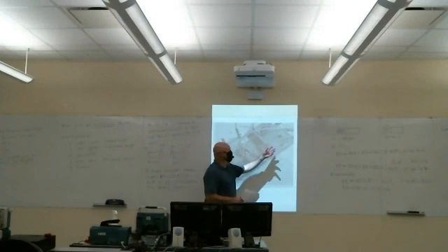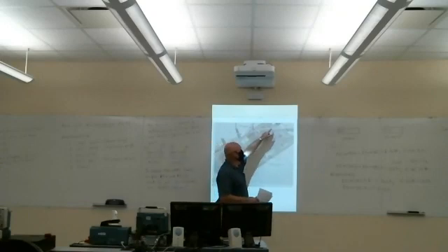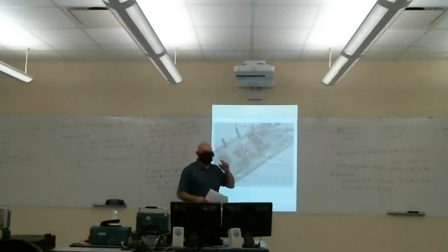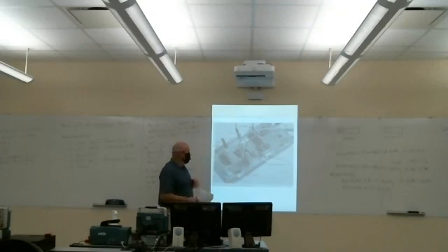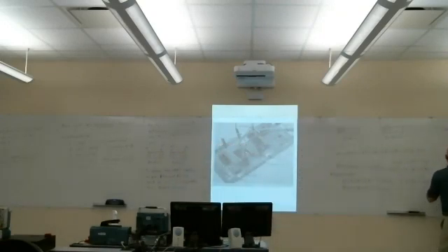It's got a whole other section of the board that's got this debugger chip on it that also provides the USB interface. That's where we plug in our USB cable. It's got a reset button on it. And then there are these jumpers that actually connect the 2 halves of the board. You can actually use this thing for development with the debugger. You can break the board in half once you're done with your debugging, and use this portion for your production microcontroller or whatever. There's a lot of features in this evaluation board that we're using. The most important one is it has the microcontroller on it.